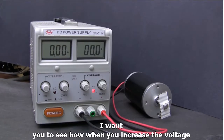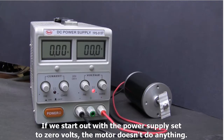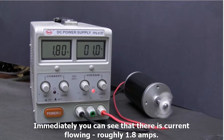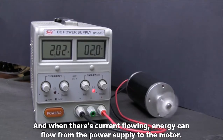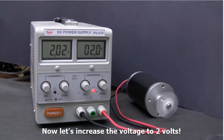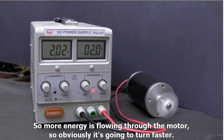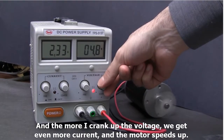I want you to see how when you increase the voltage going to the motor, more current flows. If we start out with the power supply set to 0 volts, the motor doesn't do anything. Now let's set the power supply to produce 1 volt. Immediately you can see that there's current flowing, roughly 1.8 amps. And when there's current flowing, energy can flow from the power supply to the motor. Now let's increase the voltage to 2 volts. Now that we have a bigger pushing force, more current is flowing, 2 amps. So more energy is flowing through the motor, so obviously it's going to turn faster. And the more I crank up the voltage, we get even more current and the motor speeds up.